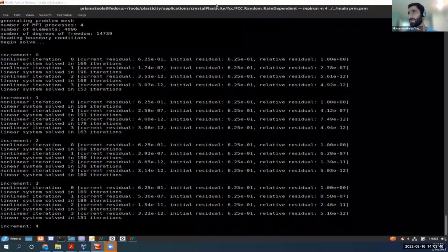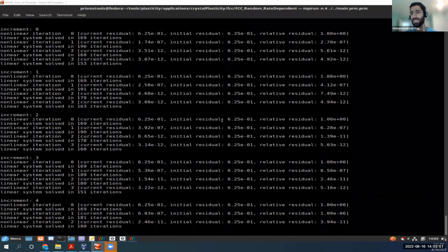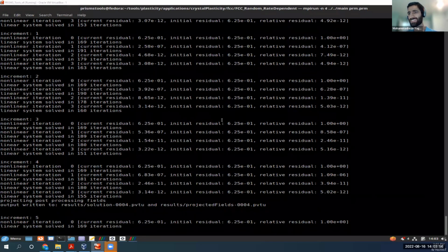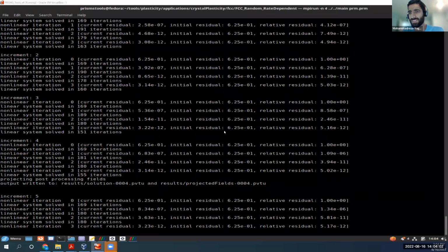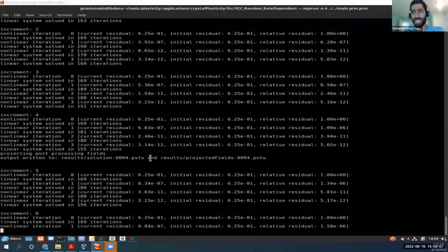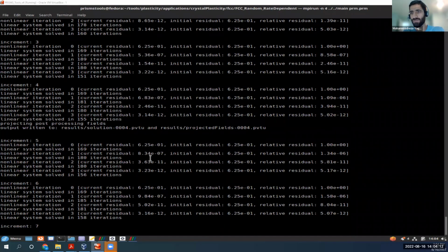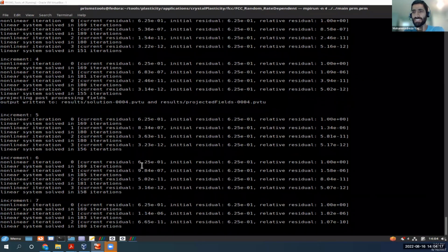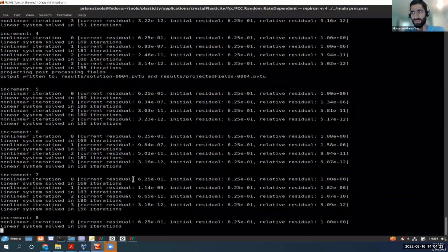Before it comes up, is this model capable of capturing size effect? Yes, you can. We have implemented a size effect, but the size effect that we implemented is through modifying the CRSS. So you can basically modify the CRSS based on the size, and you can input the size with the orientations.txt as an additional voxel information. But we haven't yet released the strength gradient model that we are trying to develop. That will be the next year release, I think.